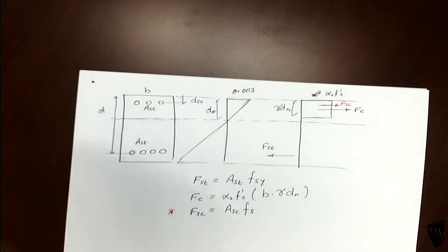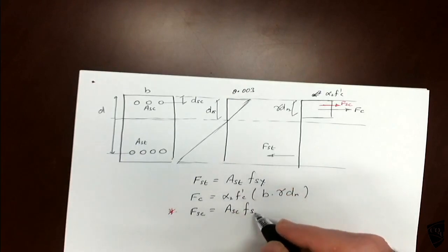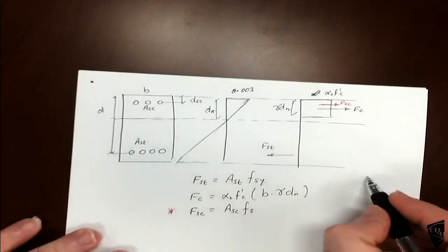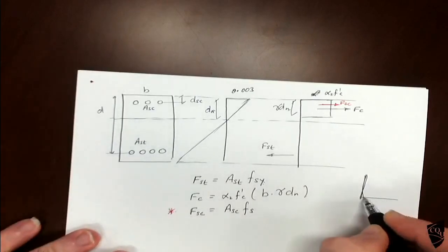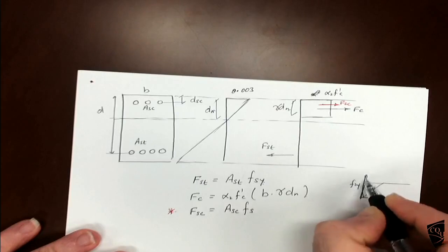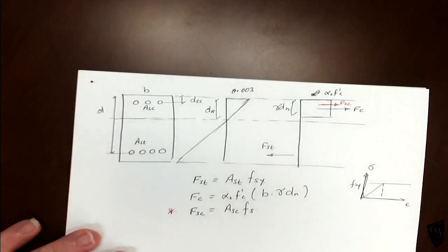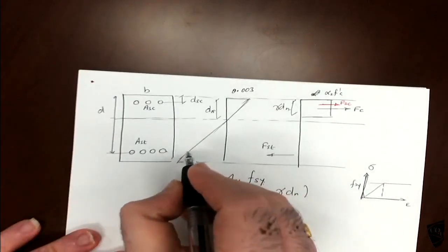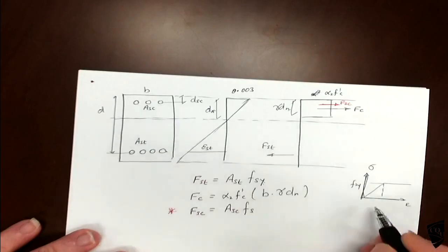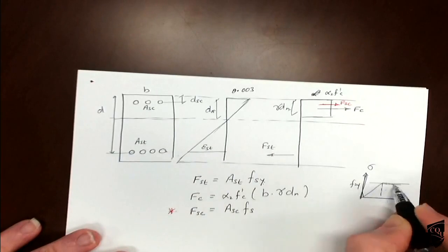Yeah, so this is the yielding strength, 500. If it has reached the yielding point, it will get the yielding stress. But if it has not reached the yielding point, then it is like that. So this is Fsy. This is stress strain. So if the steel strain has reached the yielding point, after that the stress will not increase.